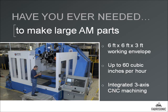All of our machines include integrated 3-axis CNC machining. This allows us to make parts to final net shape as we're building it. There's no secondary processing needed. Additionally, the 3-axis CNC machining affords the ability to make the complicated internal shapes that we've talked about previously. All of the machines are built using standard CNC technology, so tolerances as close to a half of a thou are easily achievable.